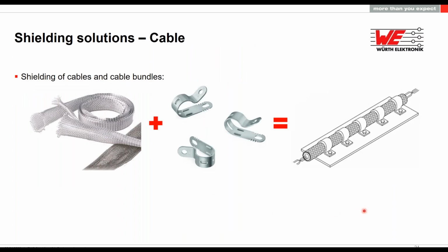So important thing is that housing does not end just on the enclosure. You need to take in account that when you have a cable, this is an extension of your housing. So you also need to shield the cable and to end it properly on both ways. This is a question I received many times. The cable needs to be ended in a proper way.